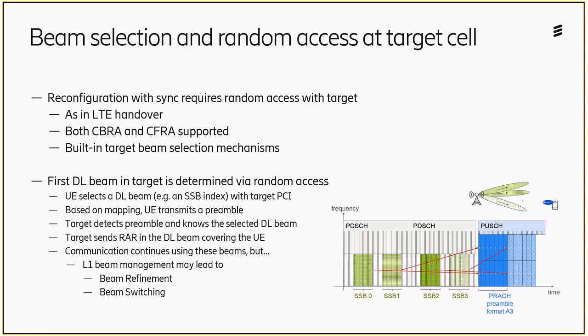So this is what this is about, that when the UE reports the beams from a target, the target has the possibility to allocate contention-free resources on a beam level. And the advantage is that I don't need to give resources for all possible beams in the target. I can do a subset. So, this UE is coming to me, and this UE is listening to my beams 1 to 5. So I want to give contention-free resources, but I only need to do it for 1 to 5 because it's likely that when it comes, it will come in 1 to 5. So this is one of the reasons that the UE reports beam measurements.